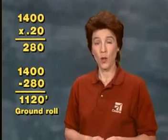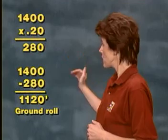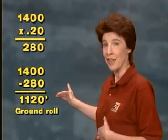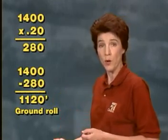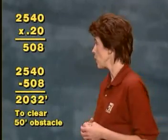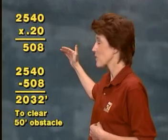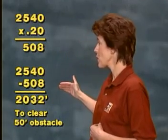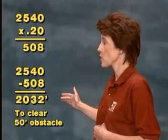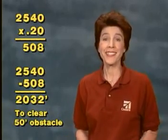To get the ground roll, you're going to take 20% of 1,400 feet, which is 280. Subtract that 280 from the 1,400 feet, and you end up with a distance of 1,120 feet for the ground roll. Now, to find out the distance that you need to clear a 50-foot obstacle, you take 20% of the 2,540 on the chart, which is 508, subtract 508 from the 2,540, and you end up with 2,032 feet, the distance to clear a 50-foot obstacle. And that's all there is to it.